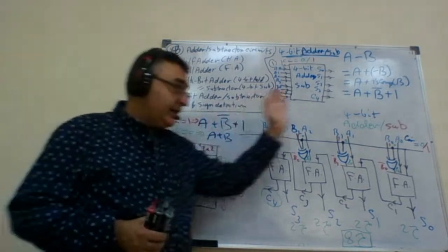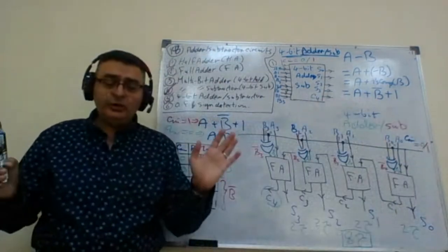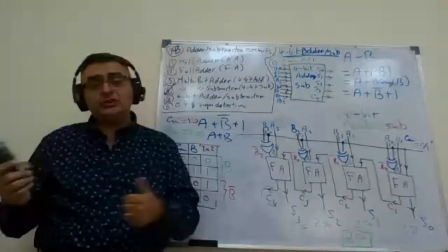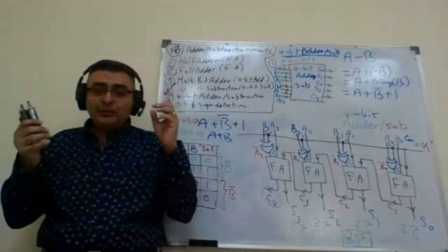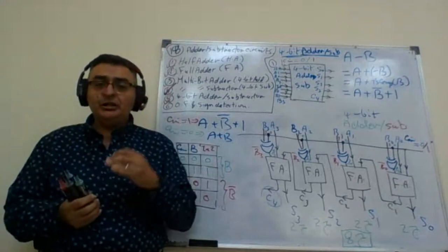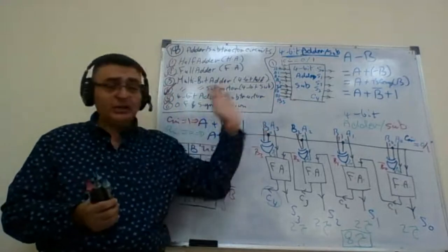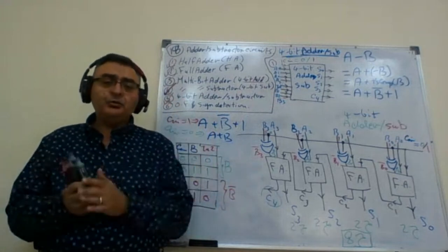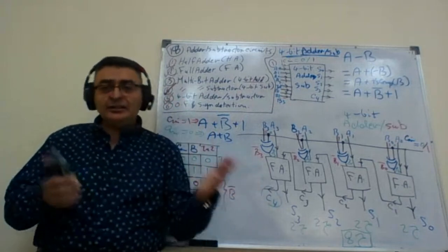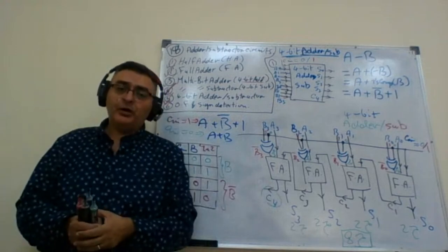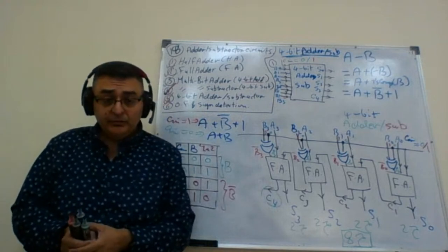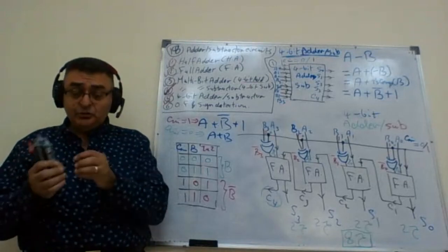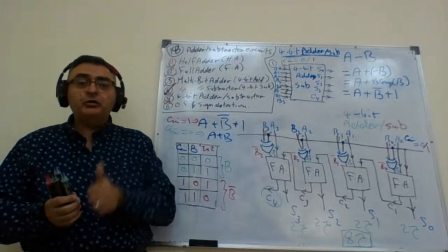By the way, this adder subtractor circuit can work whether I want to do addition or subtraction for unsigned numbers or for signed numbers. Forget about step 1, because they are matching in number of bits. Steps 2 and 3 are identical between the unsigned and signed, as we indicated in chapter number 1. However, the steps start to differ with the overflow.